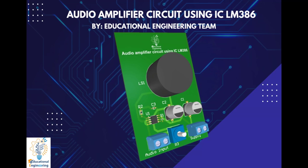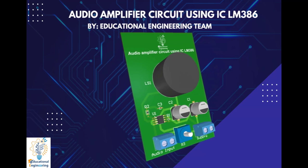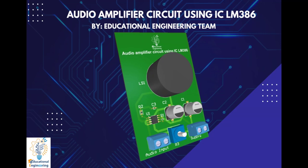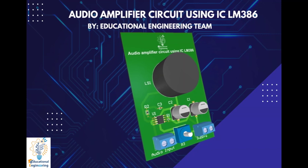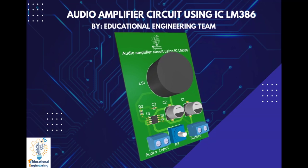This IC is a simple low-power audio amplifier used in most audio circuits for its low power consumption. This IC is capable of giving an output gain of about 200 when external components are used along with it. But when you use it without adding external components, it's capable of delivering an amplification of 20.